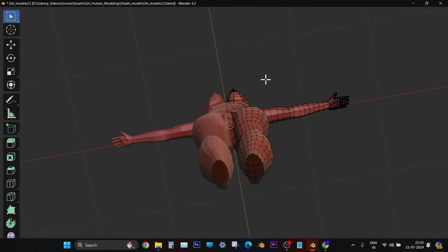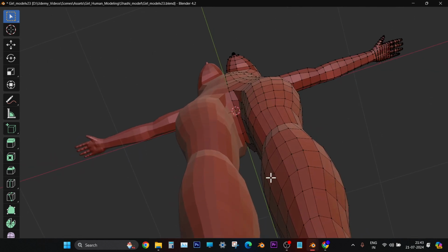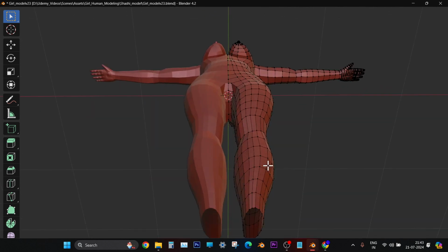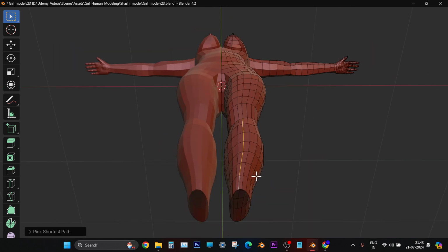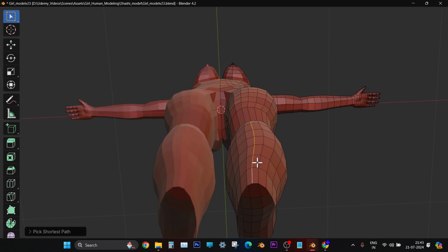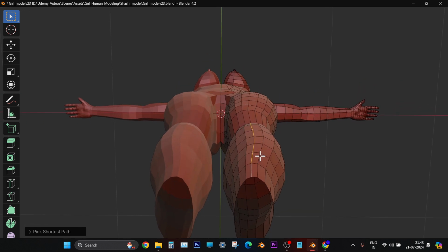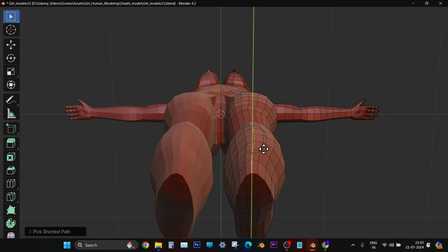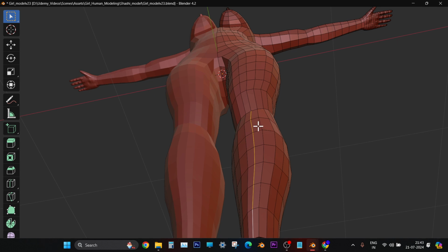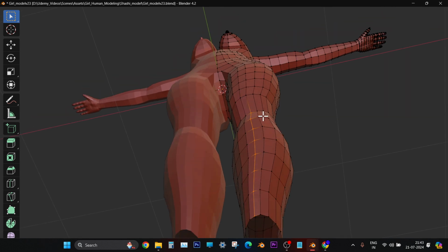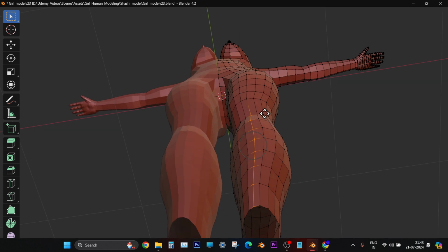So now this front portion, we can bring it forward a little, from here to here, very slightly. I'm keeping the model like this, and then press G and move it like this. Okay, right. Let's go to vertex and then press G and then Y.